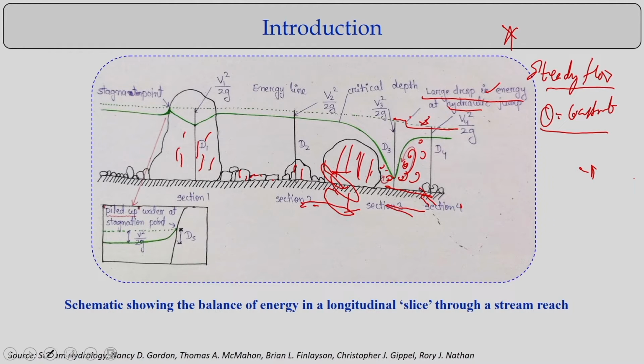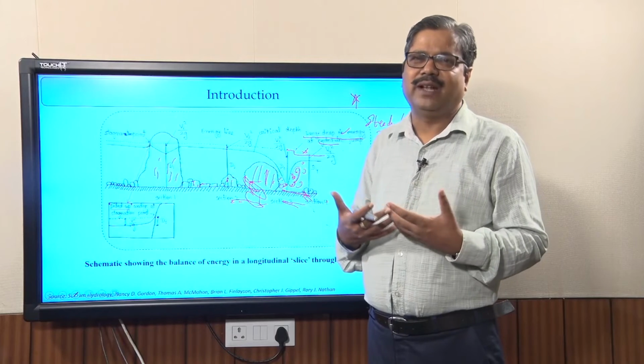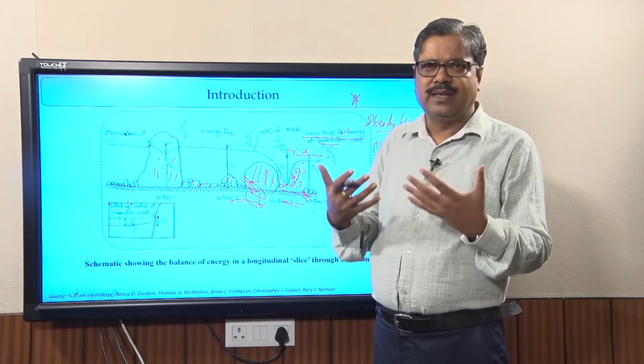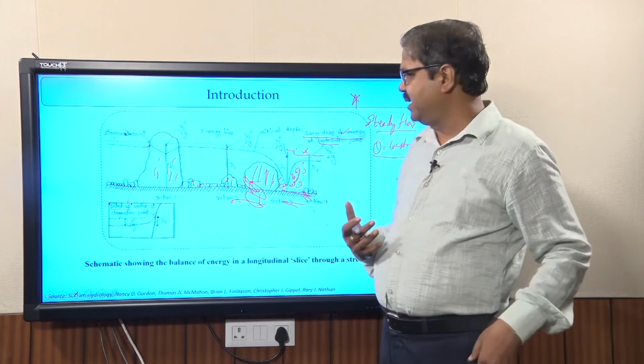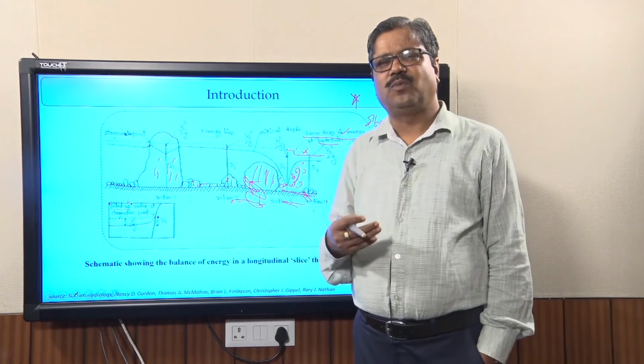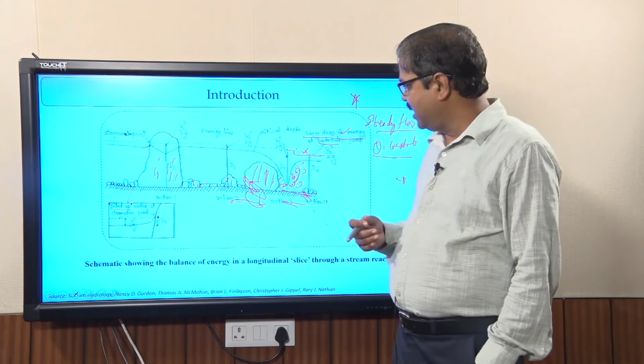and this assumption is quite valid when you look at high flow conditions or design flow conditions, what could be the extreme conditions in terms of energy dissipation, in terms of velocity variation, in terms of flow depth variations. That's what we try to know from that. That's the reason many of the steady flow analyses are also enough for us to solve these problems. So that's what we do, a steady flow analysis in terms of specific energy, specific force and critical depth analysis.